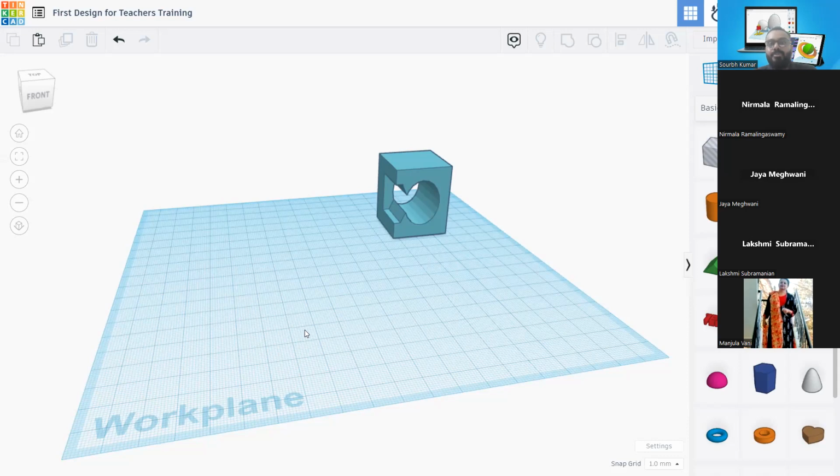So as per my perspective, if I try to design something on this TinkerCAD platform, I go for a rough sketch in my copy, like what will be the dimension of the sides, the dimension of the hole itself, and all the bevels and sides of it. Then I try to correlate with the scale we usually have in our pencil box. So you can come up with a basic consideration of how this particular object will look after printing in the real world environment.